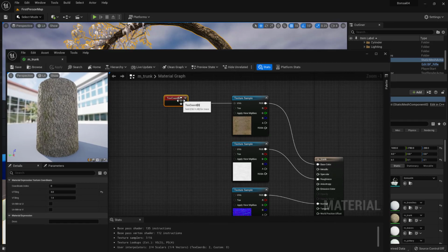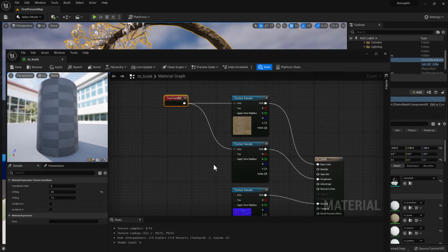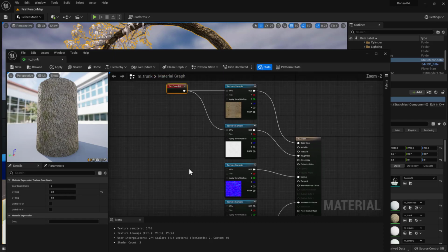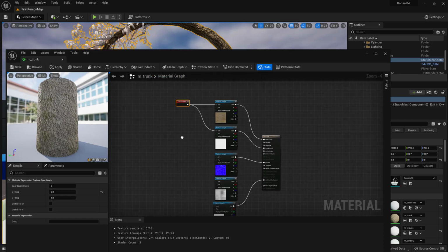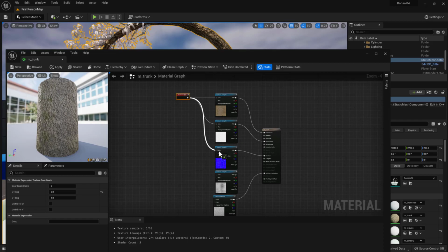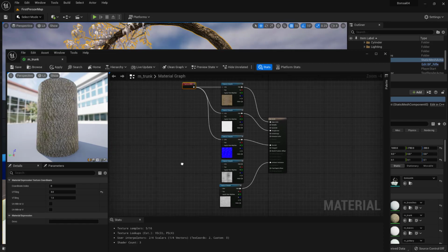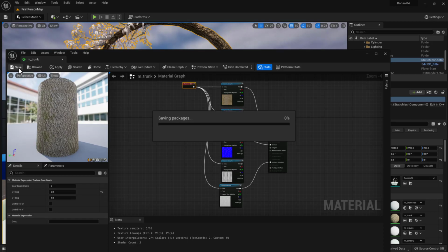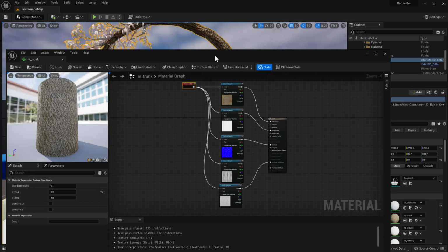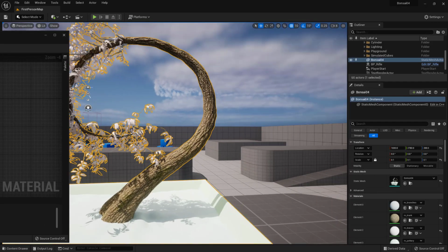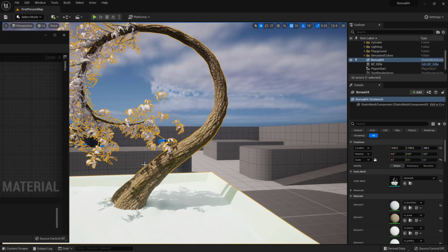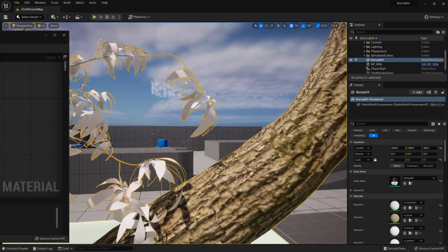Well, we made a mistake though, because we need to also pipe this into all these other ones. So if you were in Maya, you would also have a texture coordinate node going into all your materials too. Unless you look at your hypershade, you might not notice it, but it's in there as well. So this is very common. And let's see what this looks like now. Aha, so here we go. So now we see this and it's starting to look like really nice bark.